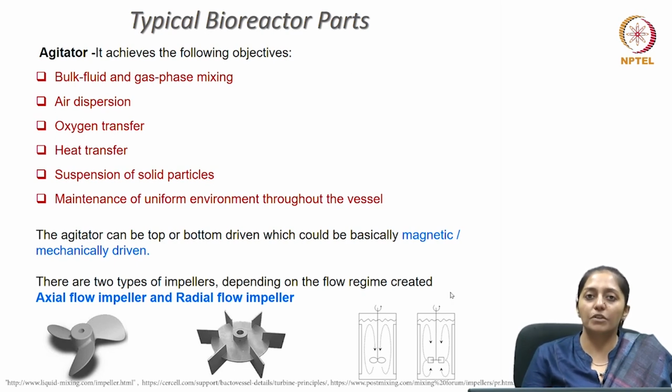So, their suspension requirements are higher, and for the shear sensitive cultures there may not be as high mixing requirements or oxygen transfer requirements. So, depending on all these factors, what kind of impellers you choose in a bioreactor design is crucial.